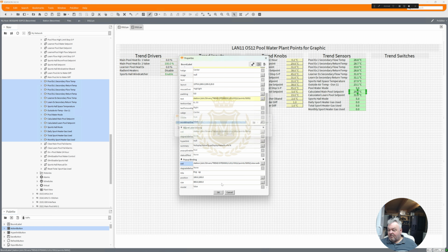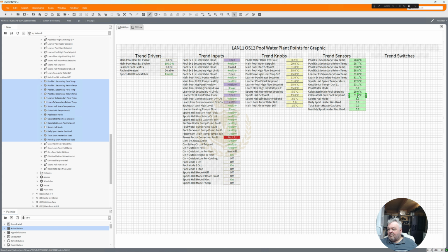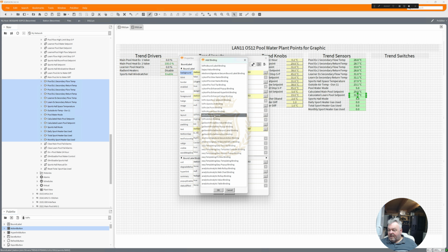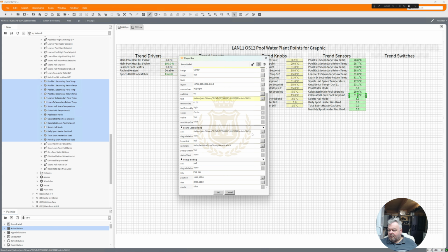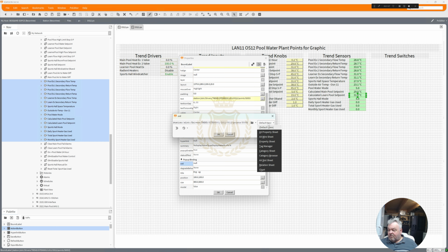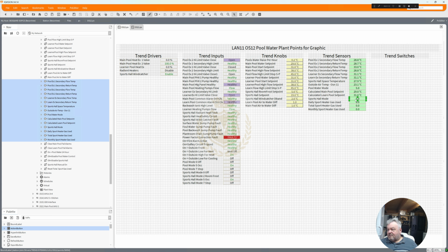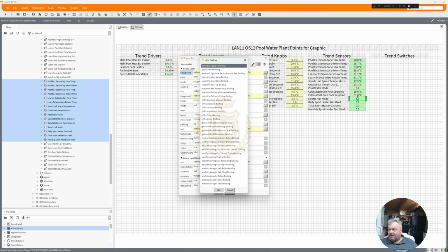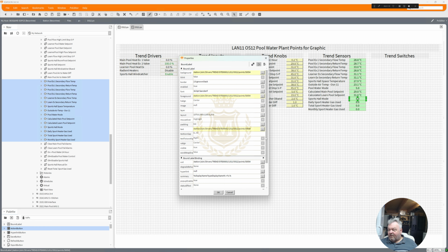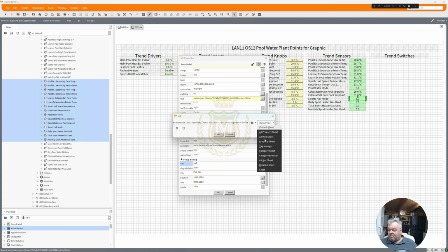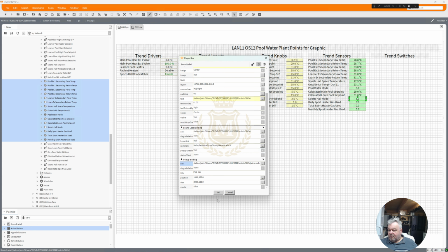It's only IQ Vision, so you've got to update the license and the points, and this is why we are doing this at the moment, because they've got a 963 on site, even though I don't think it's working, and we're now putting IQ Vision in here, talking to all the Trend outstations and sending it to the cloud supervisor so that the managers and the FM people and the engineers can log in and look at their sites without having to actually go onto site if they don't want to, which is actually quite good.